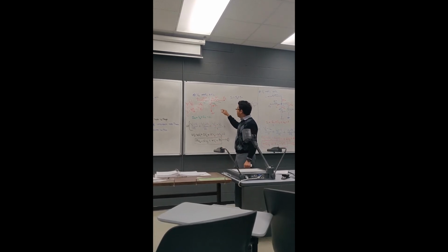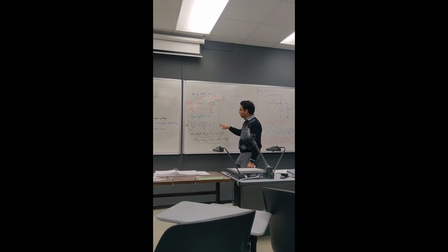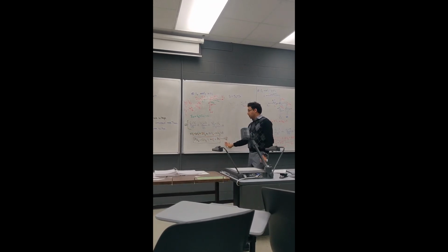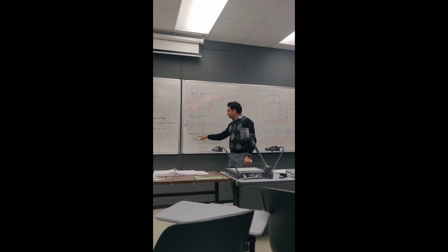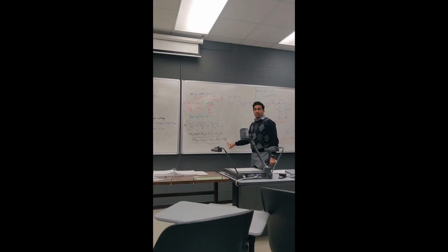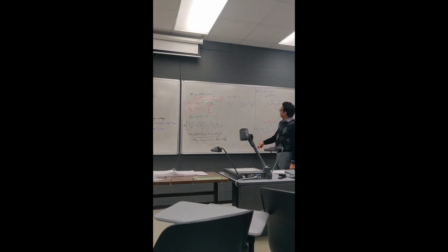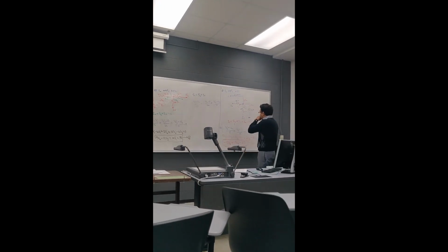And IC is V2 minus V3 over 5, and the sum must be equal to 0. Now I multiply this with the common factor 60 to make it a simple equation. I also substituted V1 equal to 20 in that equation, so I end up with a nice equation: 2 unknowns, 1 equation.